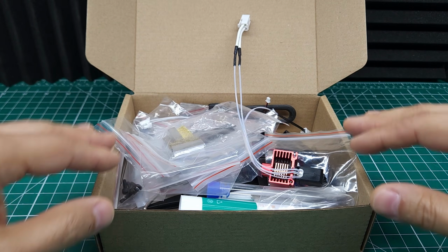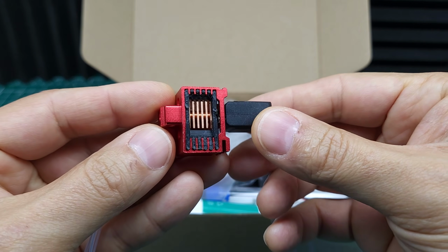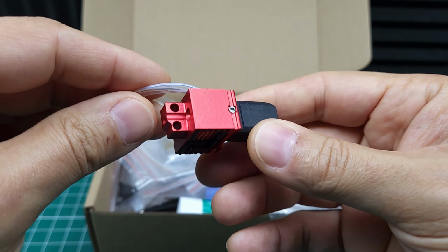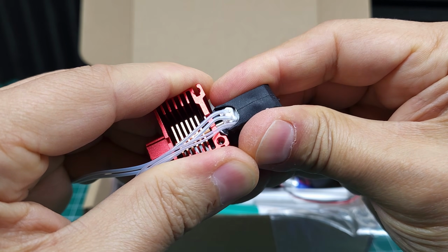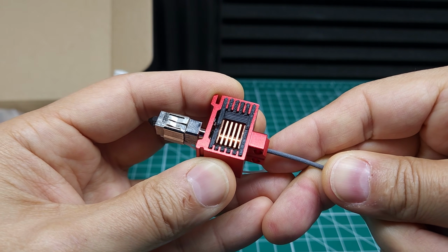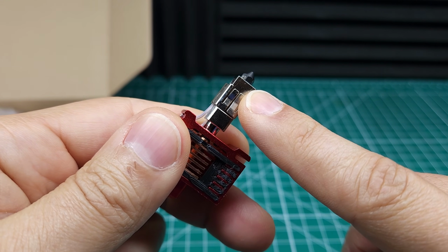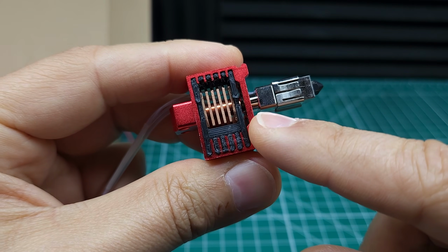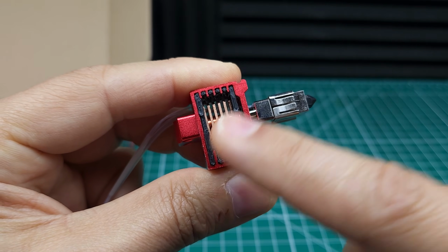I'm not sure all this stuff's going to come with the production version, but it does give us a unique opportunity. This is the right-hand extruder. If you're familiar with 3D printing and familiar with Bambu Labs 3D printers, this might look familiar because this is a clone of the Bambu Labs P1P extruder. If you're not familiar with 3D printing, the way these work is pretty simple. Essentially, through a set of gears, the filament's pushed into a hole here in the top. There's a little heater right here that heats up this area, which is known as the melt zone. And then after the filament's melted, it gets pushed out through this little nozzle. There's an area right here known as the heat break, and it prevents all the heat being created here from transferring up here and melting the filament before it's ready to be melted.